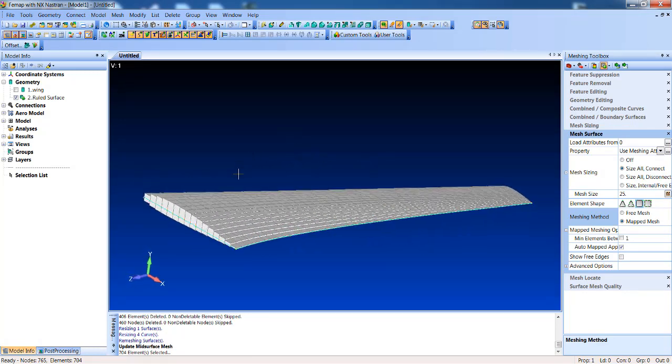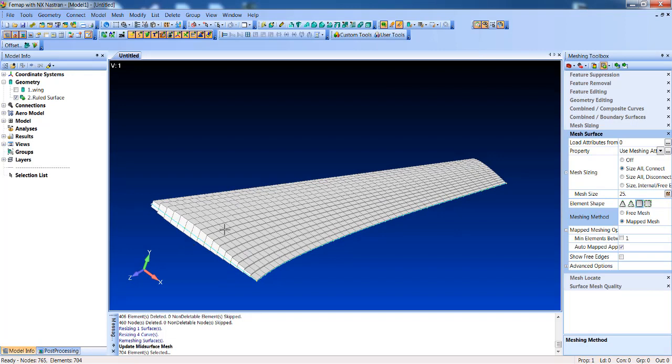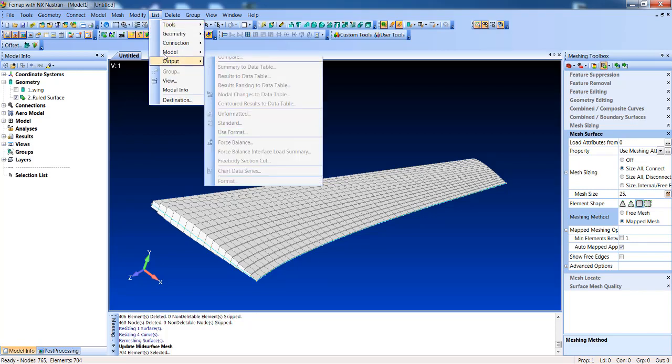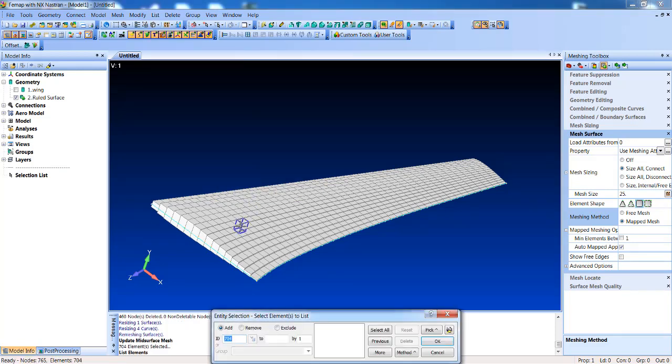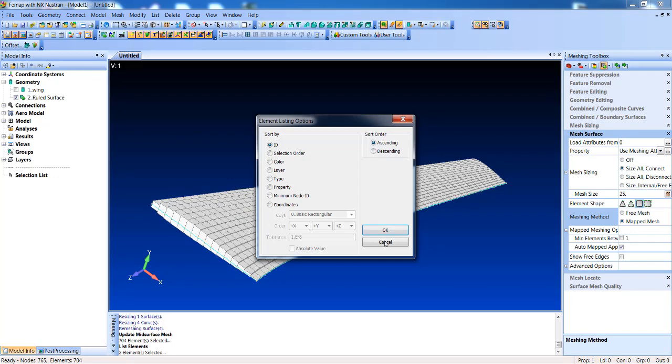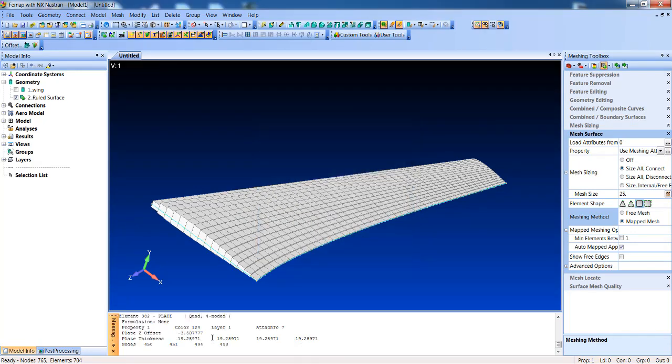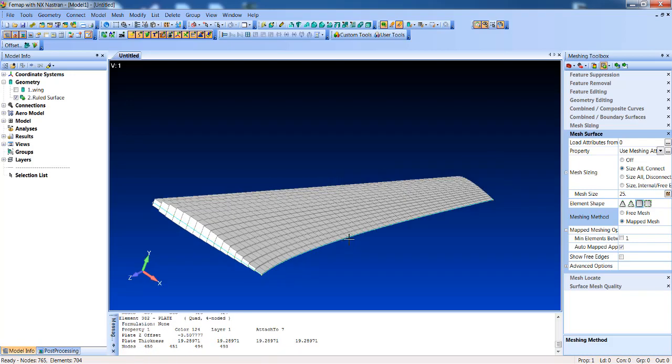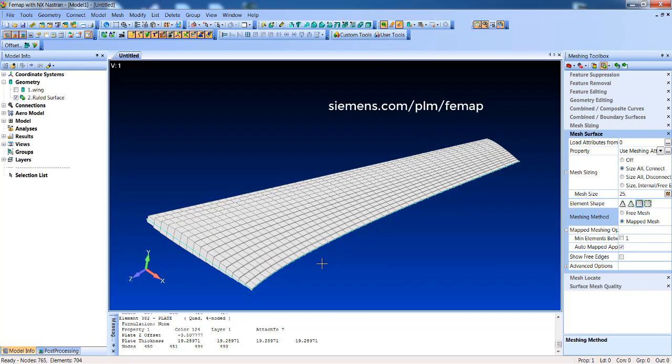So you've actually kind of really simulating this airfoil shape with a single shell element mesh, but every element's got a different property or different thicknesses. So the list model element, we'll just list 2 of them here. And you'll see that it has varying thicknesses along the element. So each element gets assigned a single thickness at its middle, but it kind of now will represent the airfoil as shell elements.